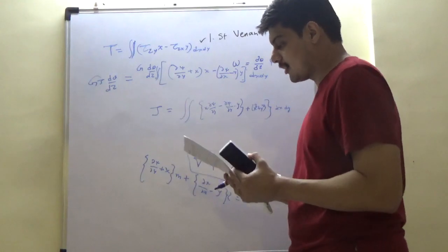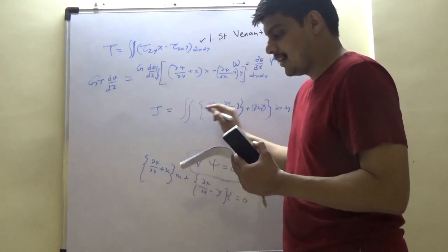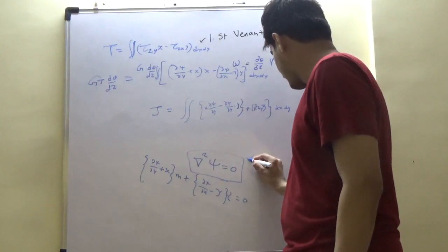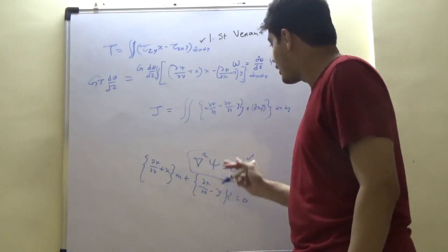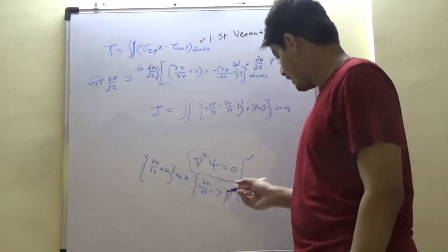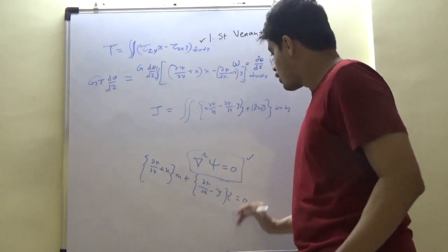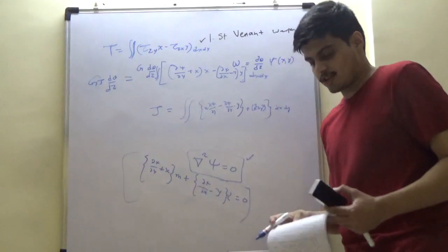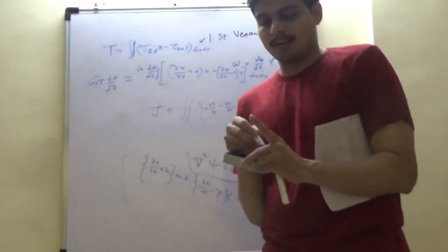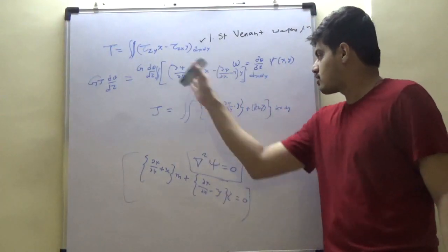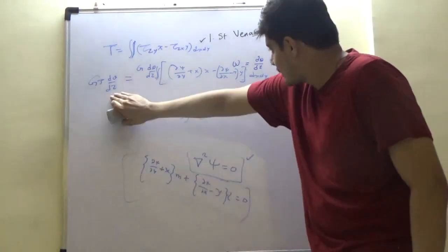So the warping function reduces to the torsion problem in determining this, which satisfies these two conditions. It has to satisfy this, which means it is a harmonic function, and then it has to satisfy this, which continues. Based on this, Saint Venant said that my warping function is easy to determine, similar to stress, so that W is easy to understand. So this is a theoretical framework.